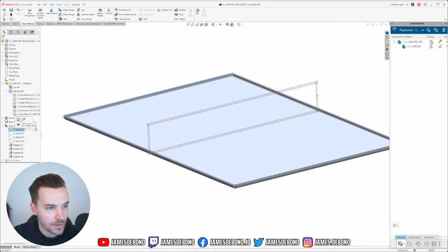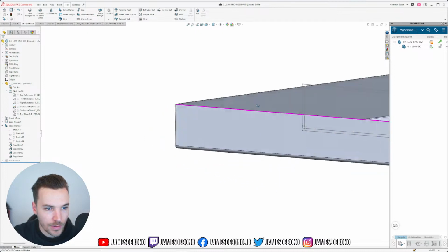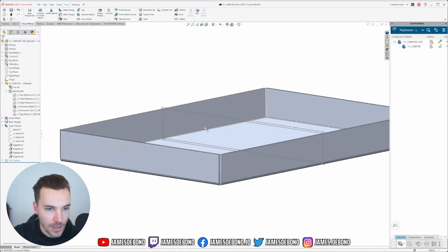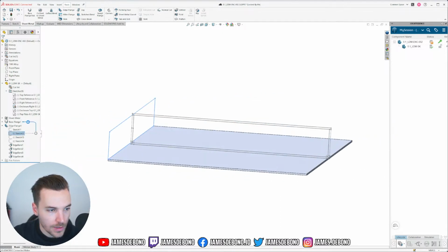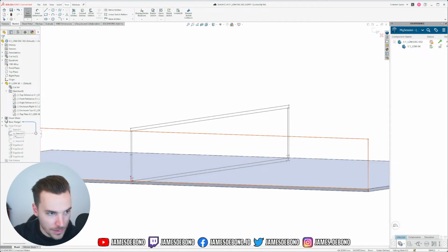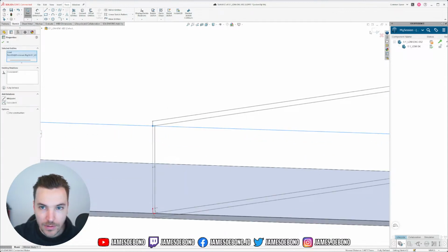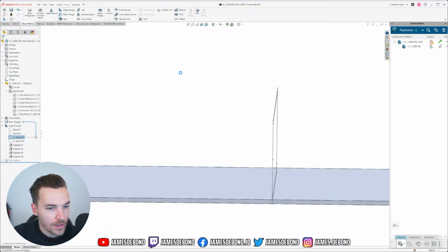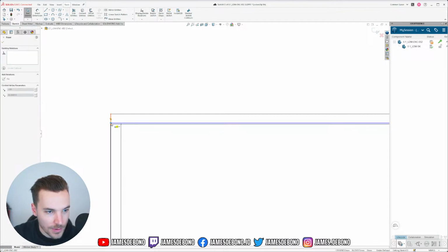So I can edit the sketch and drag it up to this point of my skeleton model that I set up in yesterday's stream, and now all of the other sides are going to match. Just because I'm a little bit obsessive compulsive and I don't like seeing these little hyphens here, which means that the sketch is undefined, I'm going to define all of these sketches. You don't need to do this, but you know, I'm a weird guy, so that's what I'm going to do.